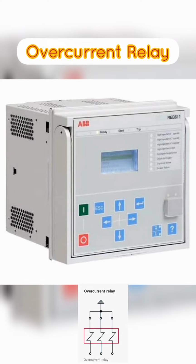In an electrical substation, overcurrent relays are installed to protect the equipment in the substation, such as transformers, circuit breakers, and bus bars, from overcurrent conditions. Overcurrent conditions can be caused by short circuits, ground faults, or overloading. There are two main types of overcurrent relays used in electrical substations: instantaneous and time-delayed. Instantaneous overcurrent relays trip the associated circuit breakers immediately when the current exceeds a certain preset level, while time-delayed overcurrent relays have a time delay before tripping the circuit breaker to allow for temporary overloads.